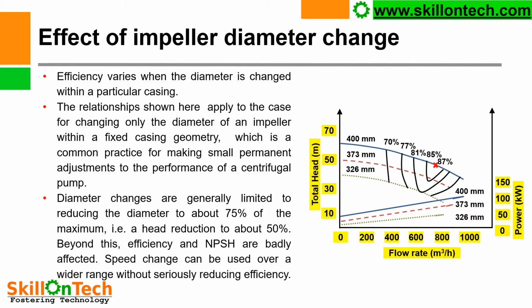If your pump impeller diameters are changed, they can affect pump efficiency also. So here you can see in this picture where the diameters of the pump are changed and efficiencies are also accordingly changing. Impeller diameter changes are done within particular permissible limits. Beyond this, they can affect NPSH and efficiency.